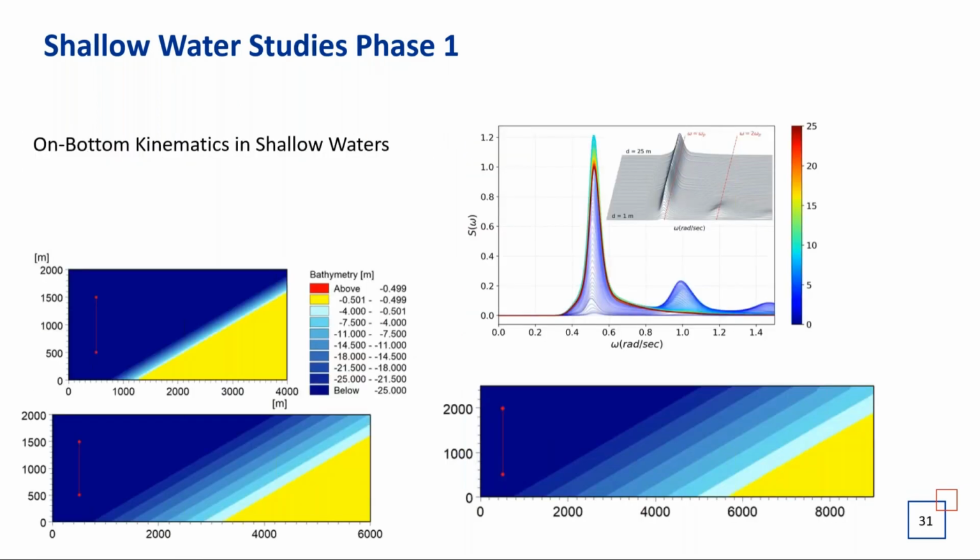And we sort of started at, say, 25, 27 meter water depth, and then came back to the shore, following the sea spectrum and seeing how that changes. We use the software called Mike, which is a DHI software, very popularly used for coastal engineering. And we did it for a small range of wave heights